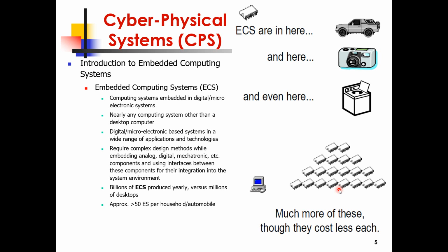Whether the wafer is 6 inches in diameter or 50 centimeters, the steps are the same. The amount of leverage and efficiency that you get from processing this area versus this one is tremendous. You get a lot more area, more chips, but you have to do the same thing. You have to put the wafer through all the same steps. And if you're doing high volume, that drives the cost down. And so these chips are everywhere.